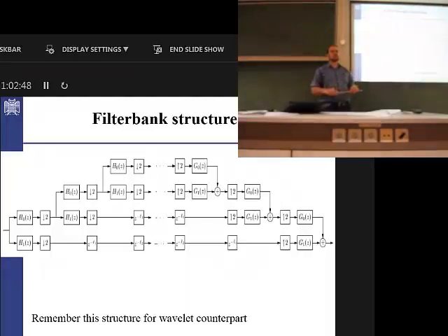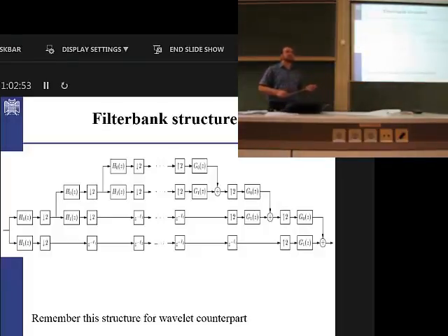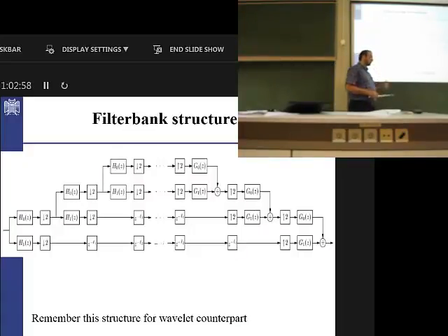But the idea is, as I mentioned, we need to have different channels that can respect the conditions or the constraints that we have in order to have perfect reconstruction. So if you have the perfect reconstruction possibility, it means that whatever process you make in the middle block, you're sure that the beginning block and the ending block will not add that much distortion or aliasing to the signal. So you should just take care of the middle block.